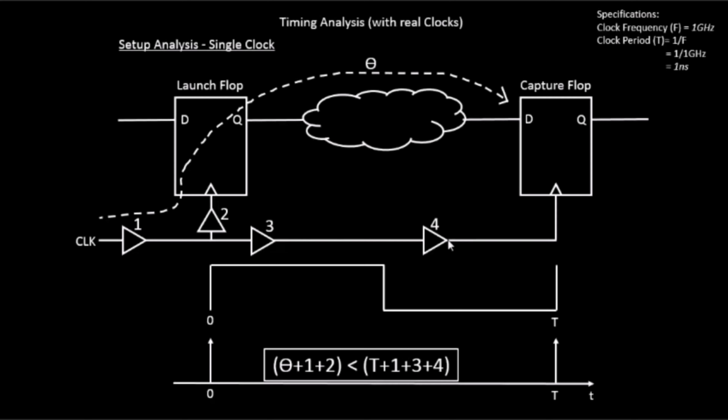Next, when the clock network was ideal, the rising edge at capital T was appearing after one clock period T, at this point. But now, since we have the clock buffers and a small amount of delay over here, the next edge at T has to move through this complete network and then hit over here.